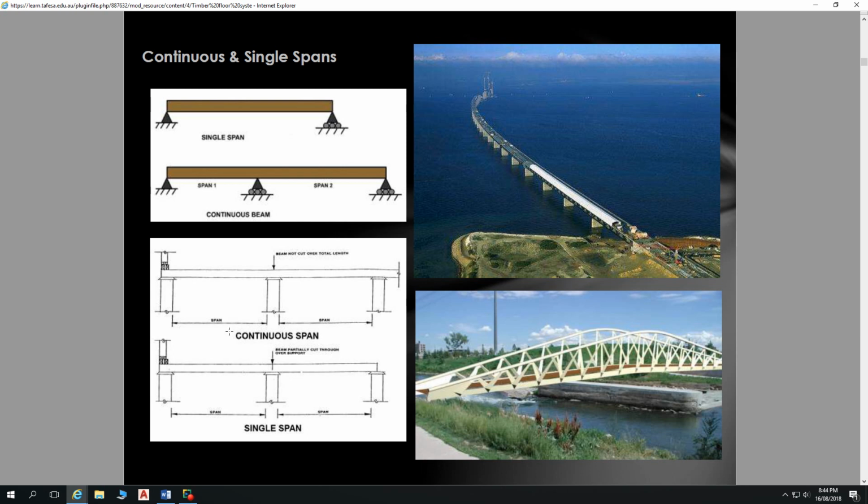There's not much. So that's a consideration if you're retrofitting old buildings and you're having to work out, okay, what sort of loads can those joists take? Can we put a wall on here that's transferring some load? Maybe we can, but that's going to be affected by whether those joists or bearers are cut over top of stumps.